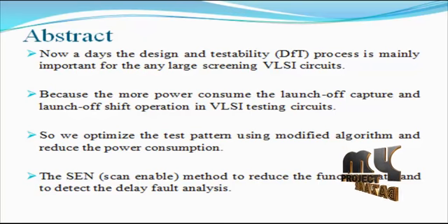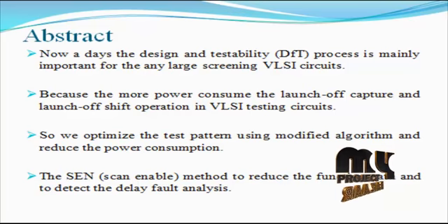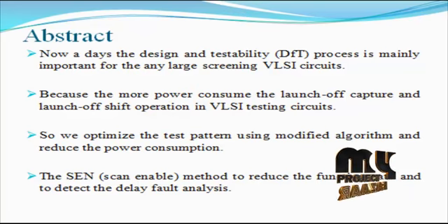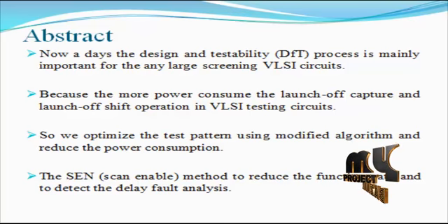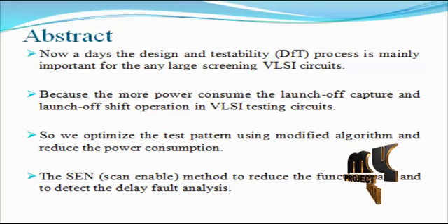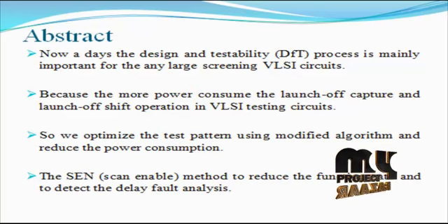Next, we will see the abstract for the product. At-speed and even faster-than-at-speed testing of VLSI circuits aims at high quality screening of the circuit by targeting performance related faults. On the one hand, a compact test set with highly effective patterns, each detecting multiple delay faults, is desired for low cost. On the other hand, such patterns increase the switching activity during the launch and capture operation.